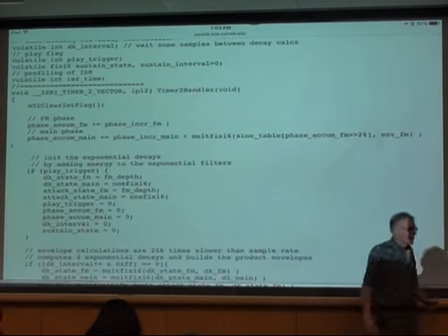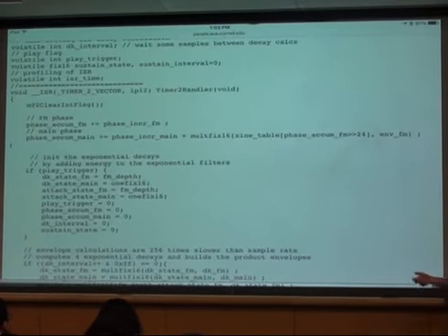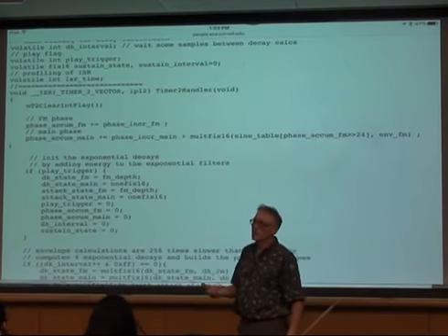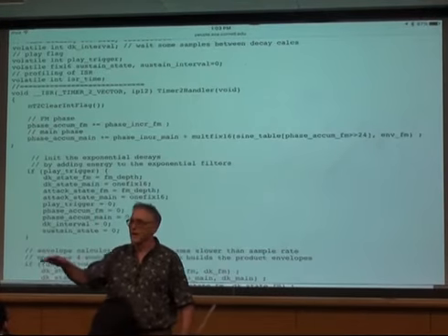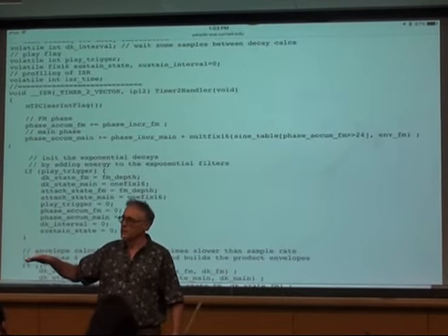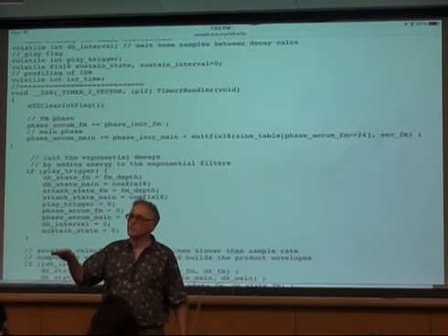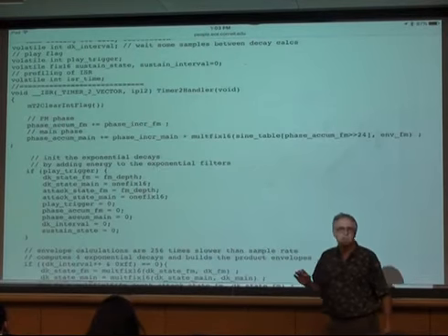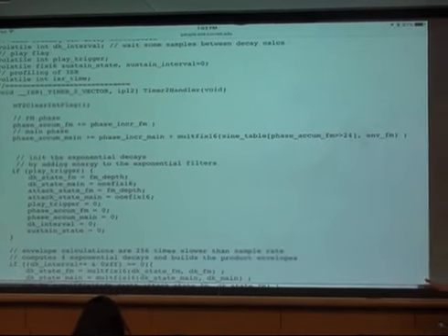And the reason for that is that the time scales are so different. You want to do the audio synthesis at 20 kilohertz, but you can't afford to calculate the very slow decay at 20 kilohertz because you don't have enough arithmetic accuracy. So what you have to do is slow down the calculation of the envelope by a factor of 256 or so, so it's going at more like 100 hertz or so.